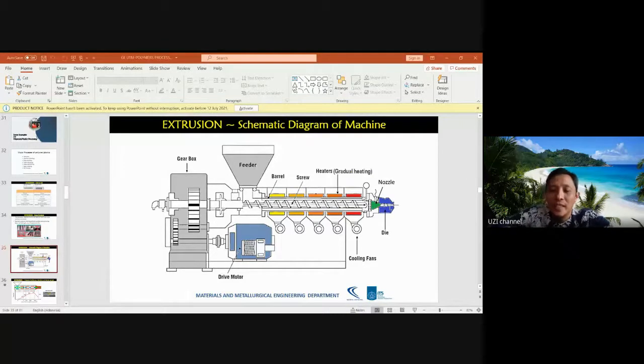Then we cool it to keep the polymer in the deformed condition. For example, if we make a curve like this, we heat up the polymer and compress it, and after it cools we can release the compression and the mold. We get the final product of the heat-compressed polymer.